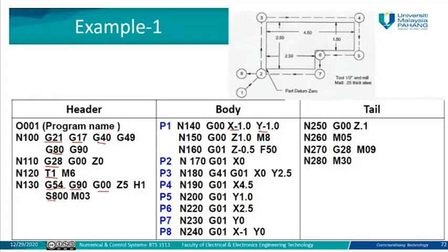Then when it goes for cutting, when we use G01, the depth is 0.5, so it will go to -0.5 of Z here. Then it will continue with G01, go to X0, X0.25, X0.45, Y0.1, and so on until the 8 values are complete. All these parts, from 0.1 to 0.8, you just place the cutter on the border of this workpiece, then go to cut by using G01.